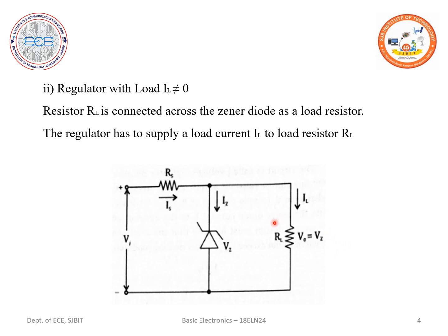Now, the Zener current, which we call Iz, must always be above Iz min. The higher limit of current allowed to flow in the circuit depends on the power dissipating capability of the components used. Again, in this we have two kinds: one is the line regulation and the other one is the load regulation. That is, in case of a regulator with load, I can expect these two kinds of regulation.